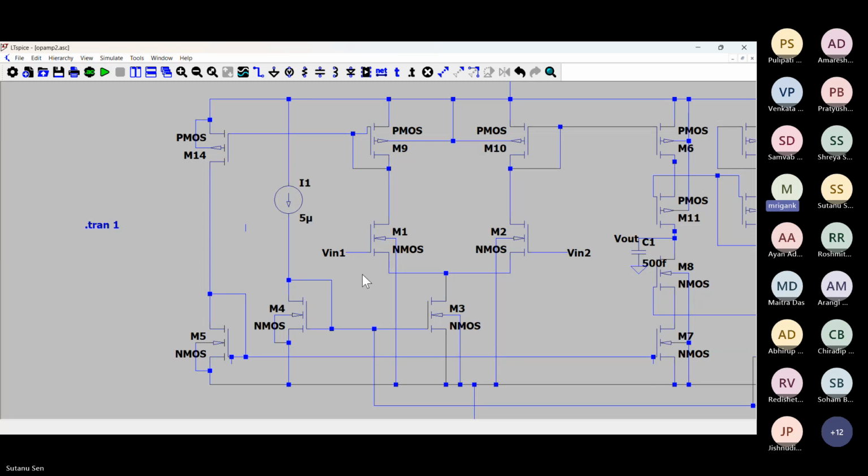On the other side, M6 is having three other transistors in stack. As a result, the source to drain voltage of M6 is coming small. Despite the same VGS, M6 is sinking lesser current as compared to what M7 would have. To compensate for that, the output voltage goes down so that the current in both of the branches becomes equal. Ultimately, it has to be the same, right? M6 current has to be the same as M7 current.